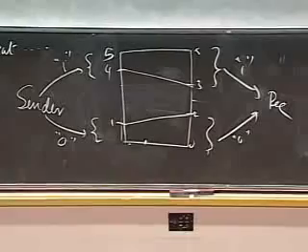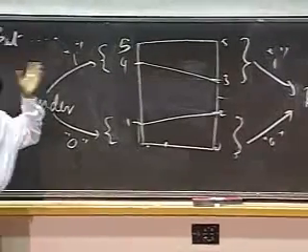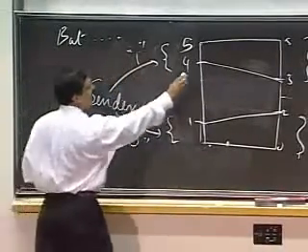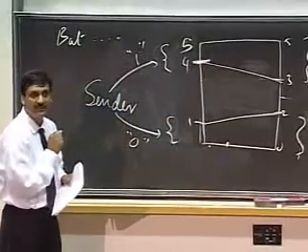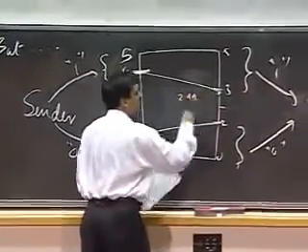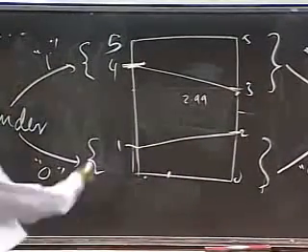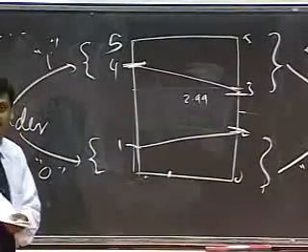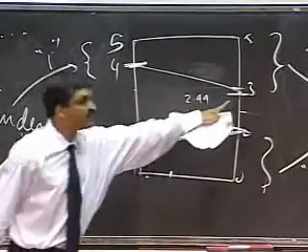So now I do have some noise margin. Can someone tell me what's the noise margin here for a 1? 1 volt. And the reason is that the lowest voltage a sender can send is 4 volts. If the 4 leaks down to 2.99, that's in the forbidden region. I'm in trouble. So notice that the lowest value that the receiver can receive is 3 volts.